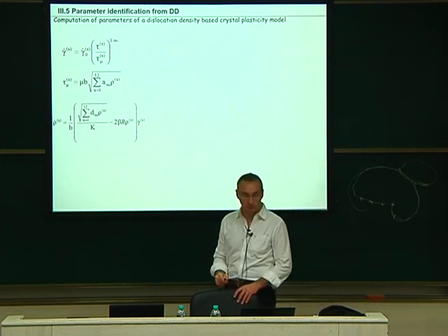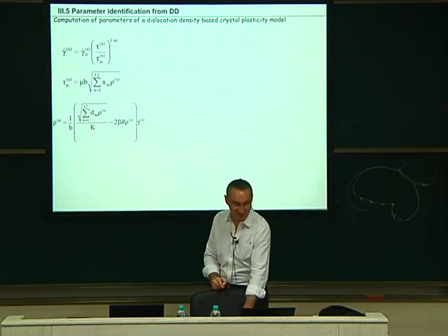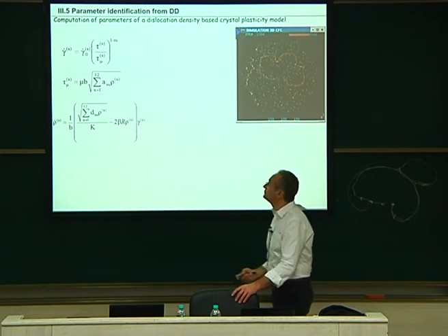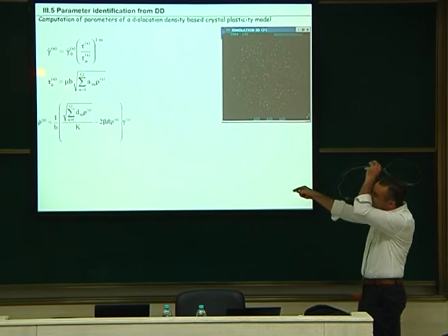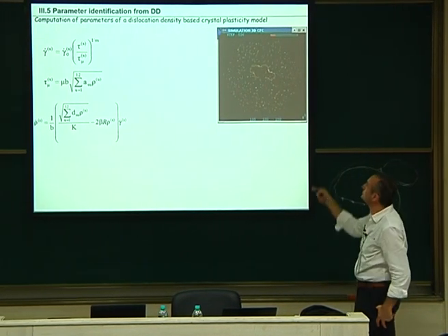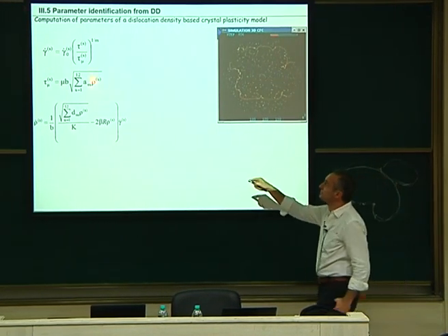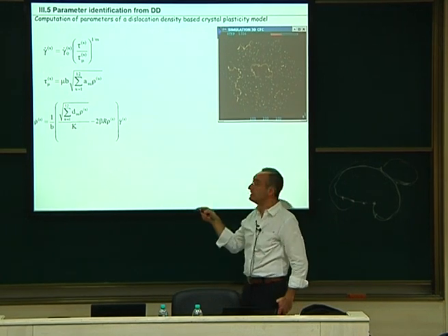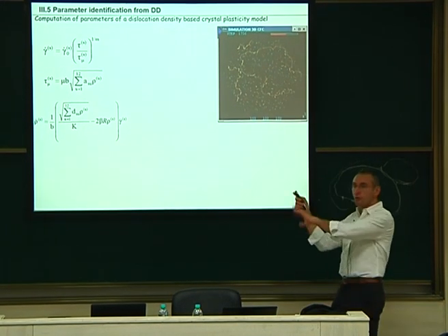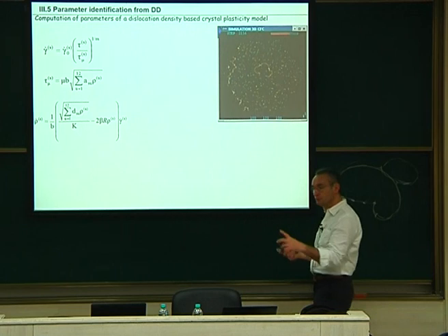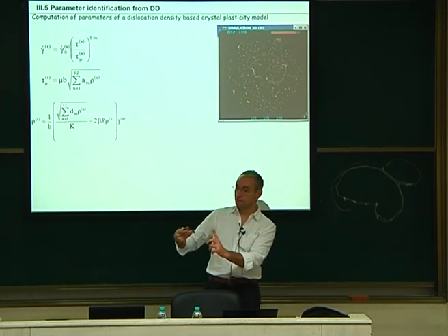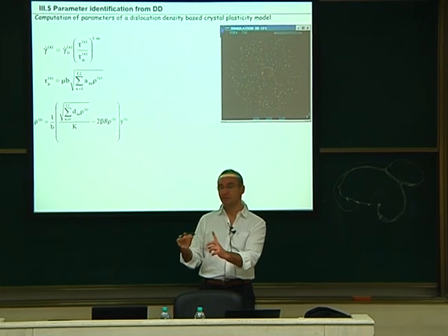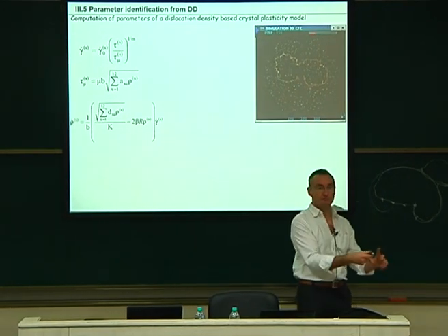So how can we do that using DD? Using DD, things are quite simple. What you can do is put a dislocation line like this on the system S. Let's say it's an orange dislocation on S. You put many dislocations on the system U, as forest dislocations like that, of all orientations. Because I told you, if you put all the same orientation, dislocations which are lazy will find the angles for which the interaction is the minimum, and then it will go through for free.